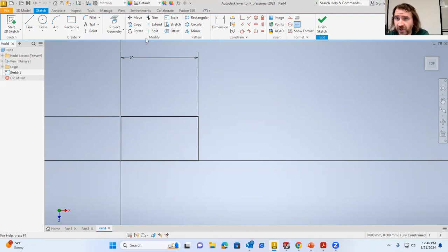So very, very quick. So we need to go to fillet, and our fillet radius is 10. And we need to fillet this corner and this corner, just like that with our fillet tool. Remember, with our fillet tool in the sketch mode, we just need to select the two lines or the corner that's being eliminated here and made into a curve, like we've talked about in other videos about the fillet tool, and add that, and we should be good.